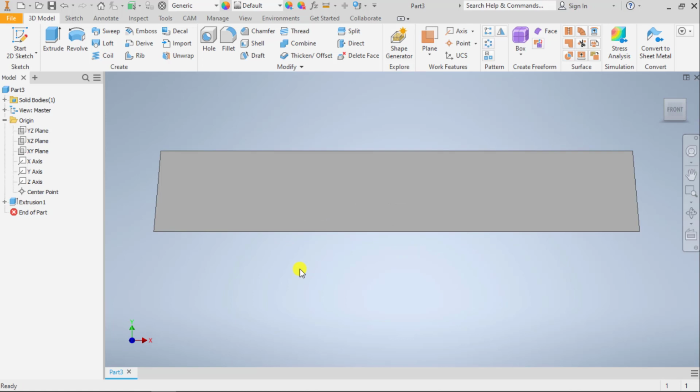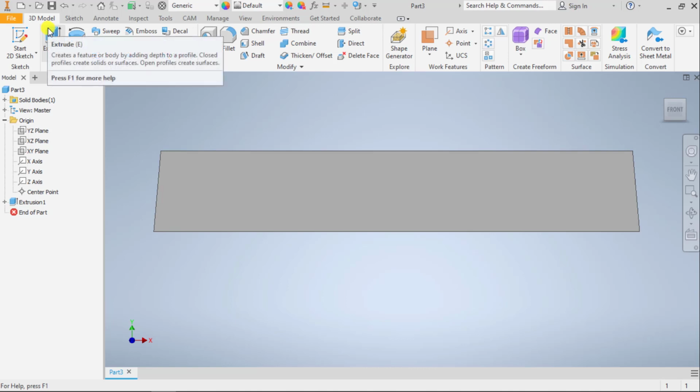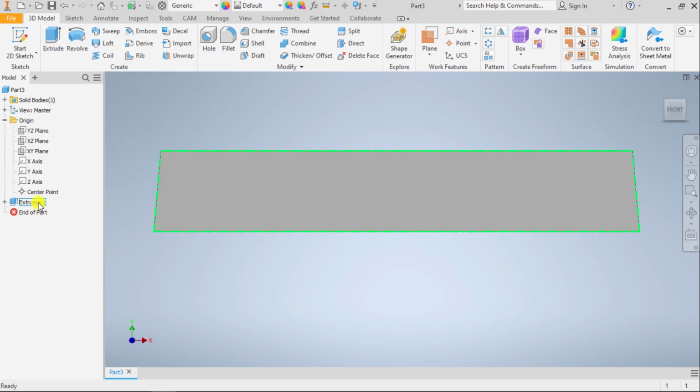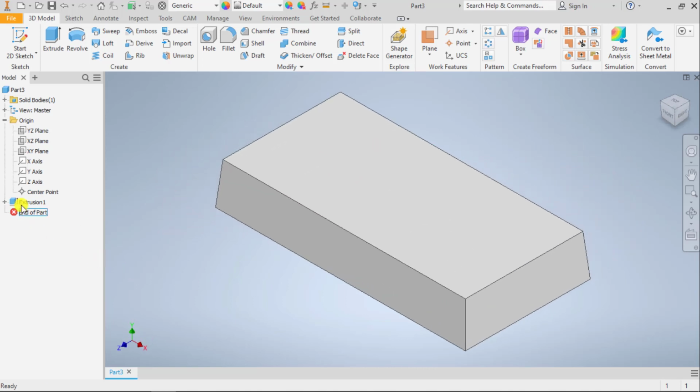We talked a little bit ago in another video about modifying sketches, and I said, you would never start a new test to do test corrections on a test you took for, let's say, history. You will never need to start a new extrusion in order to modify an extrusion that we already have. So if we take a look at our model tree, we see extrusion 1, and that has consumed sketch 1. Okay? So now sketch 1 is not visible anymore, and it is consumed by extrusion 1.